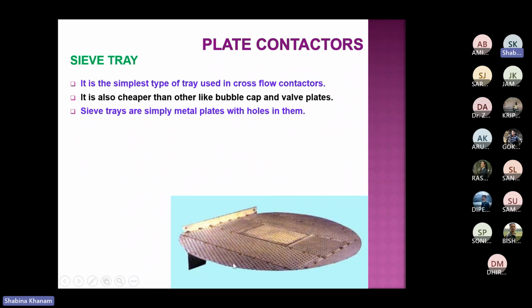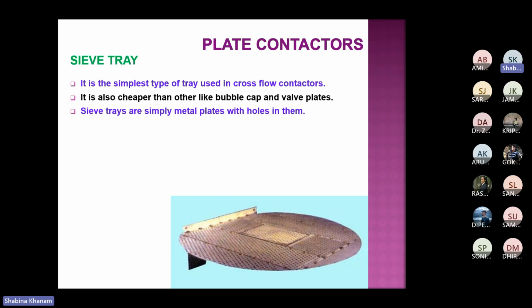In this case, these two plates are arranged side by side, and below this, a metal plate is welded, because these plates have to be at the same level. So in these sections which are placed just one after another, side by side, below we have the metal plate, and that we call the backing strip that is welded.